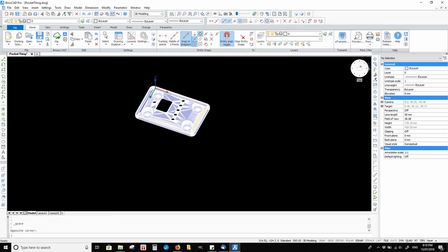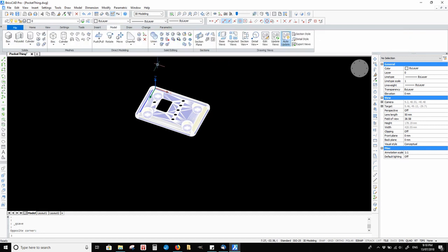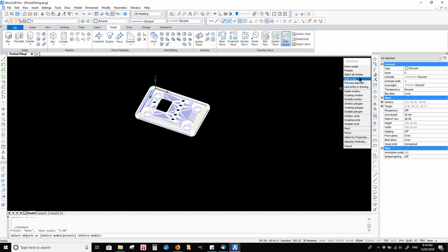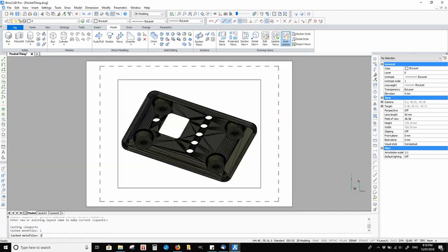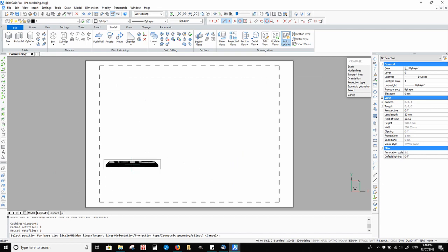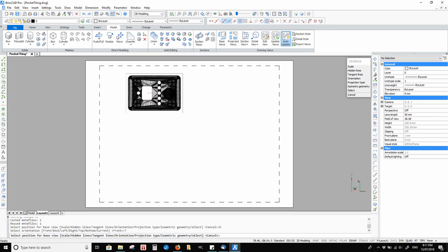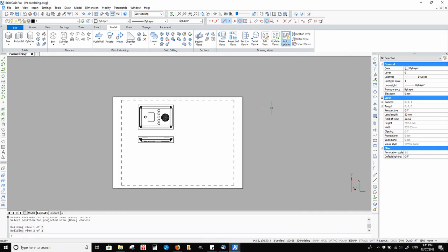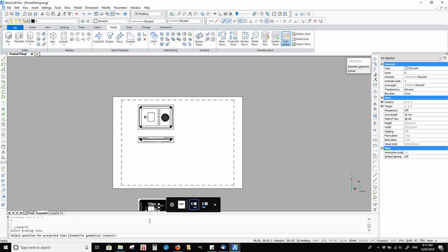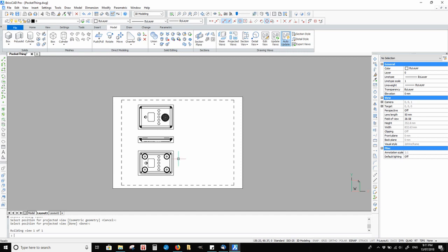They are very intensive. Next, we'll use BricsCAD's drawing view functions to create 2D views. You can use the flat shot and section plane functions if you prefer. Once the views are drawn, export them to model space.